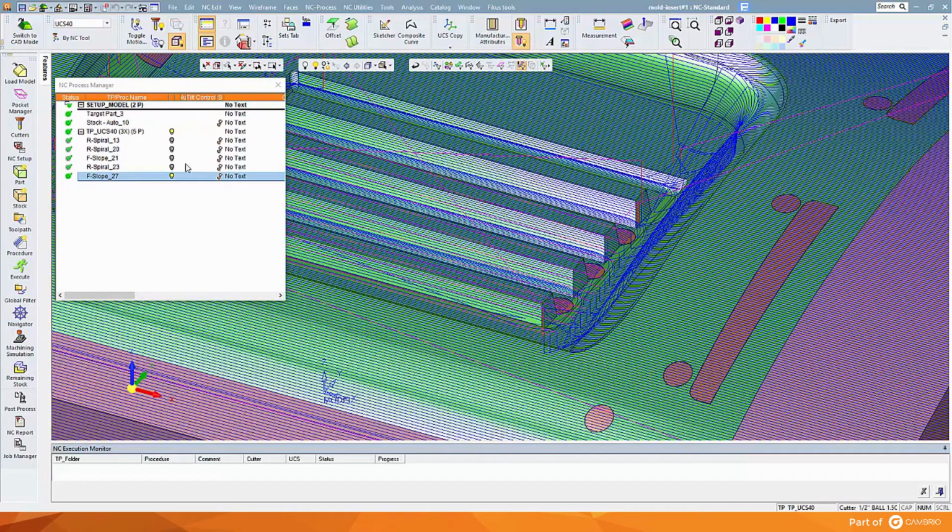For finish milling procedures, the system is capable of calculating the minimum length for a single specific tool and holder combination. Or if you prefer to work in a more structured manner, it's also capable of automatically swapping in longer cutters where they're required from the tool library.